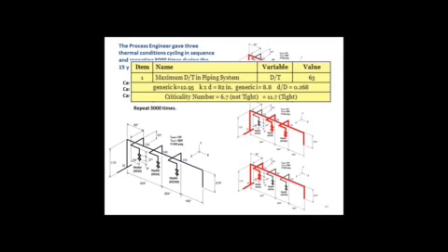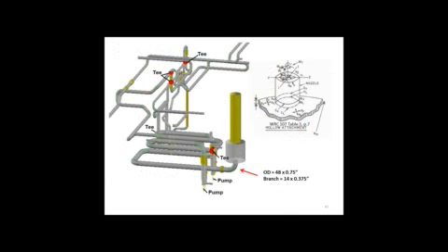So if we do the criticality analysis on this, if I considered the system not tight, it was 6.7, which is just over 5, which says, well, maybe we're interested in it, maybe not. But if we considered a tight system, the criticality number goes to 11.7, which says, yeah, you might want to think about that. So we can see that the criticality constant is definitely affected by the tightness of the system, and we want to get a good sense of when systems are tight or not, because the stresses will be significantly affected by those things. Let's go to the next system.